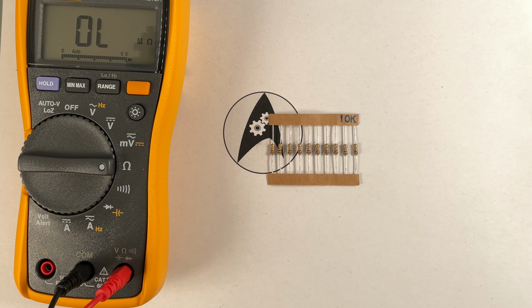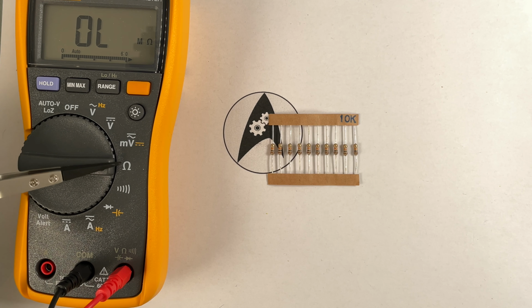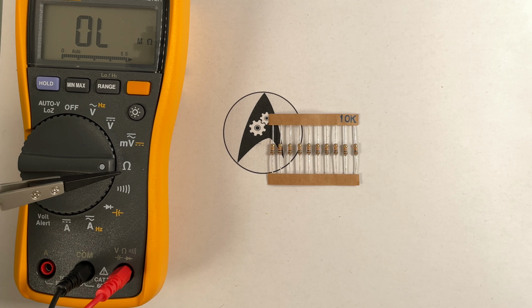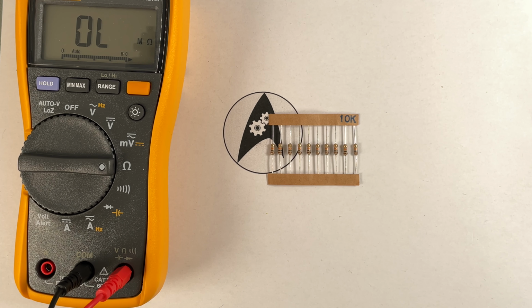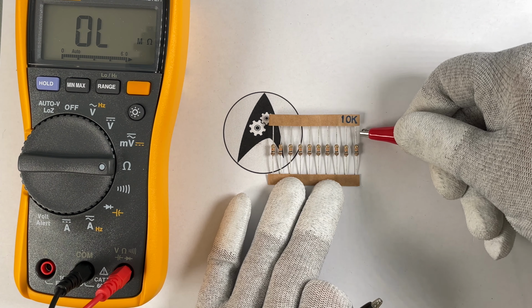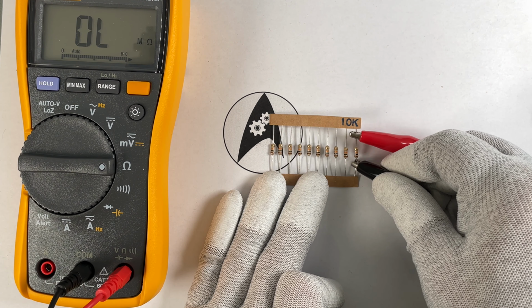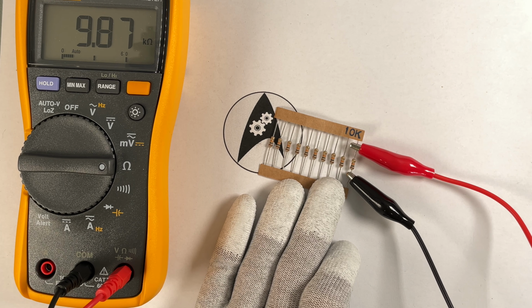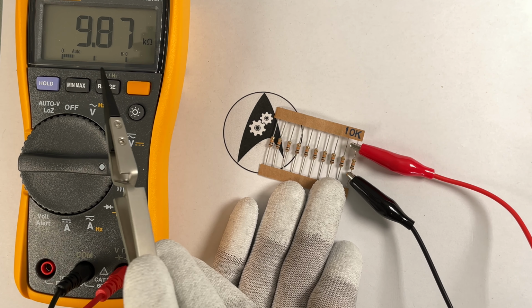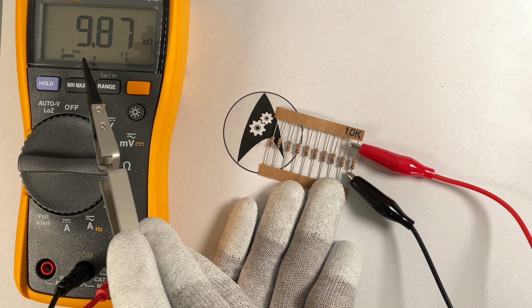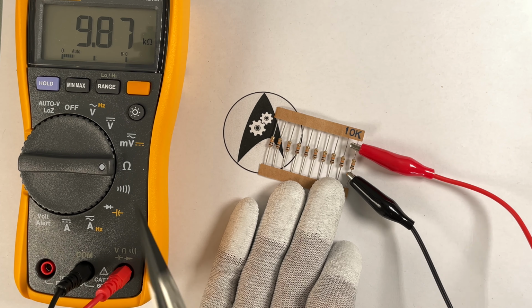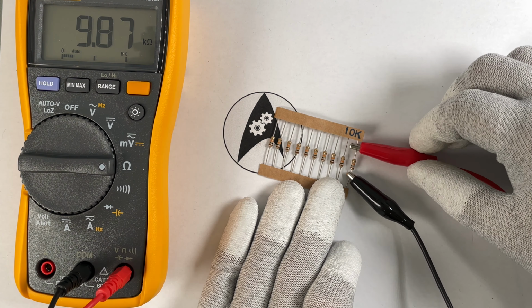What you can see here is all the range of measurements which we can take with this multimeter: voltage and current and also capacity, and now we're going to measure the resistance value by using the ohm symbol here. Now, in order to do this, we only need to connect these two measuring tips against one of the resistors and observe what's going to be displayed on the display here. The resistance value you can see here is not 10 kilo ohms, it's 9.87 kilo ohms, which is less than what we were promised, so to speak.